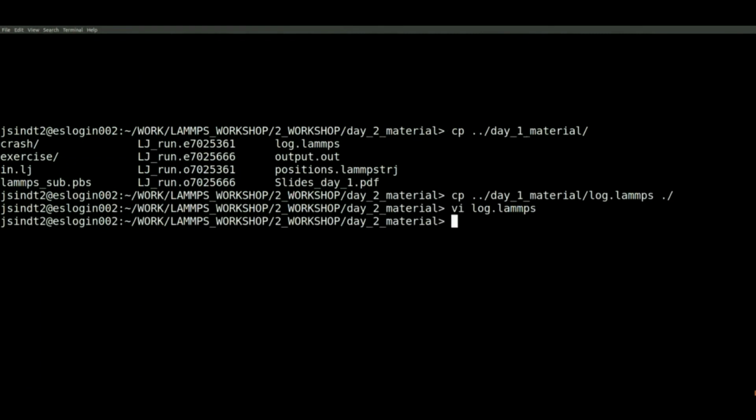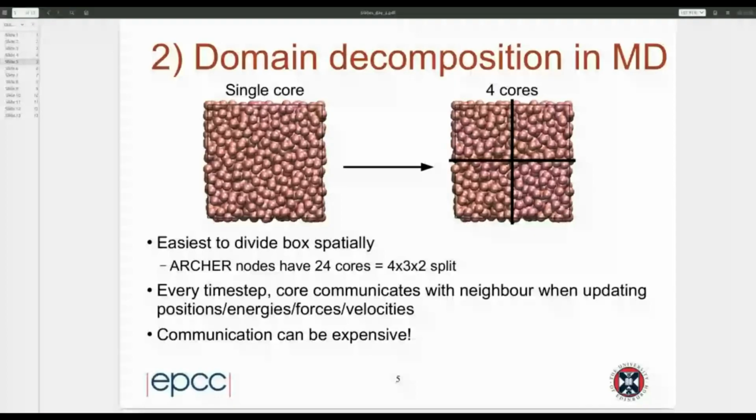Right, back to the slides. But just to emphasize while I swap over, LAMMPS does provide a ton of information. It's always worth checking out your log file if you feel that things are taking too long or things aren't running quite the way you want them to. Look at the log file because it has very nicely broken down information, and that's always the first step to speed up your simulation.